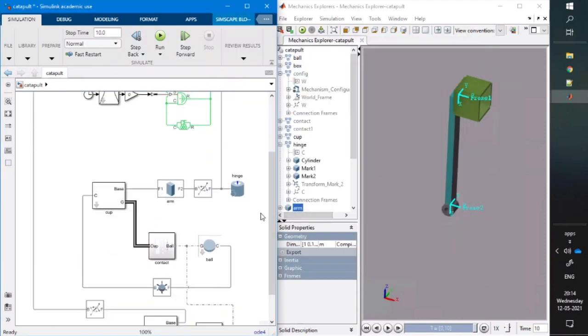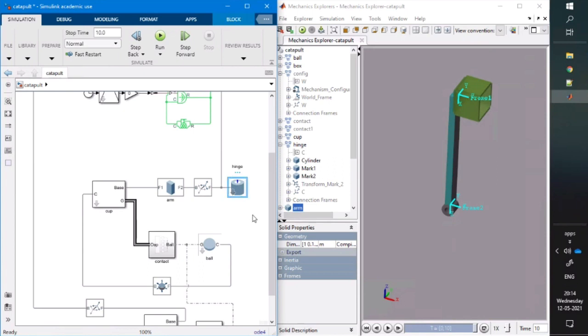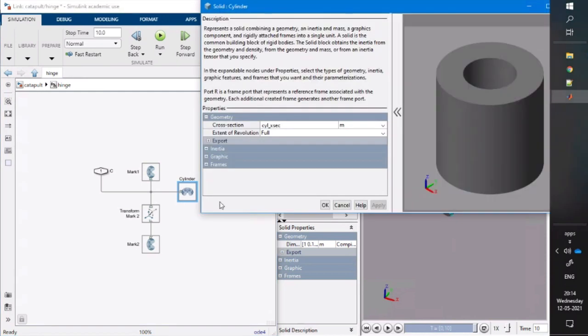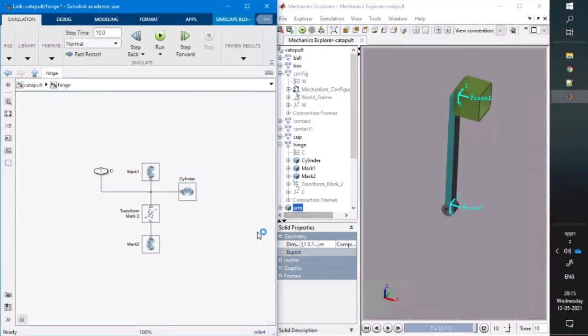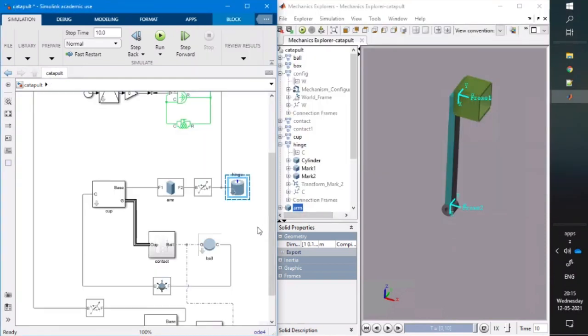So then you can again access the changes in the variables directly. So any block that you touch, they are directly variable, and all the variables can be set up. So even within the bodies, you have the variables set with cross sections everywhere. And all these variables are fully functional with all other apps. Maybe some of you might know Simulink Design Optimization, where you typically try to do response optimization, parameter estimation, sensitivity analysis, and so on. So all of this are fully capable of utilizing those apps.